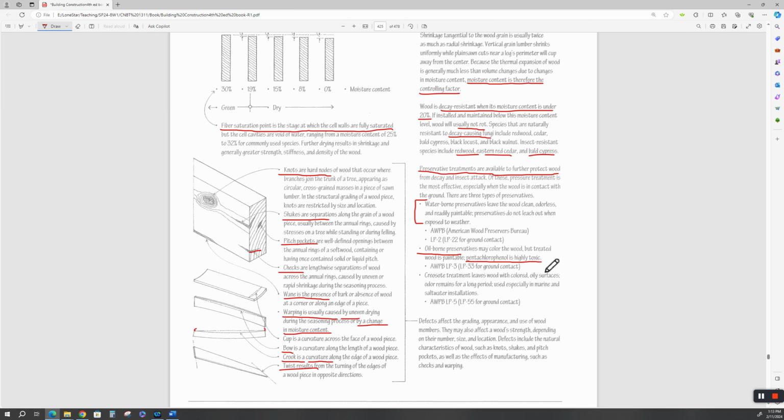And when you're cutting this, like you're going to make a corral, I used this for that guy's fence on that house in the back. He wanted a corral-like looking thing, and you had to be careful of the sawdust. So when you're cutting it with a saw, you wear a mask, because this stuff is highly toxic. Again, the American Wood Preservers Bureau labels penta-treated as LP-33 for ground contact. You can go out there to the bureau and look at all their stuff.